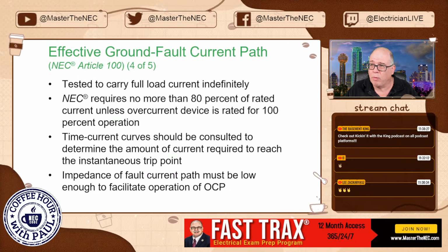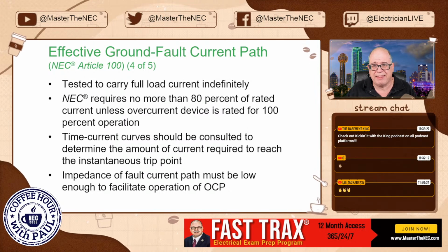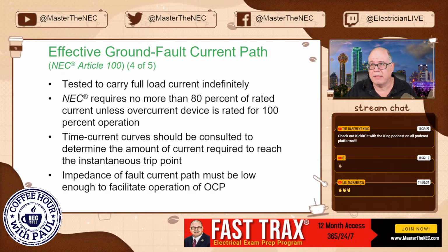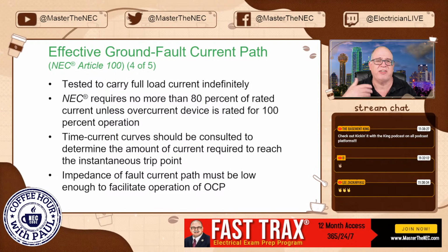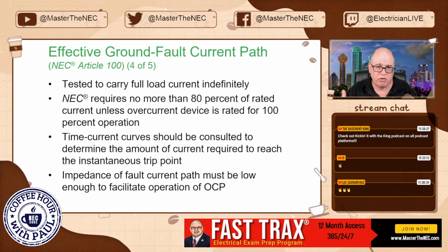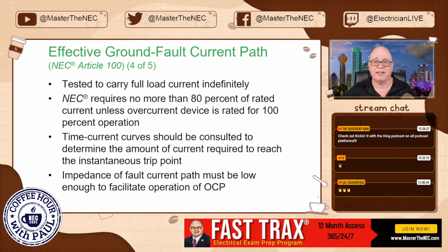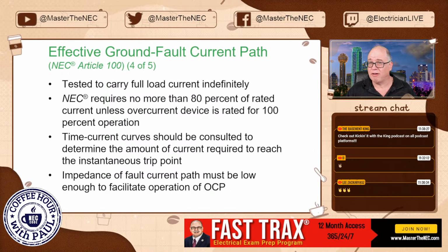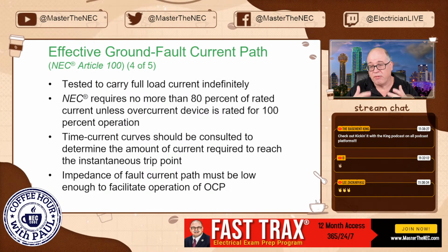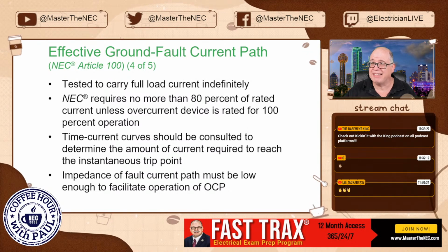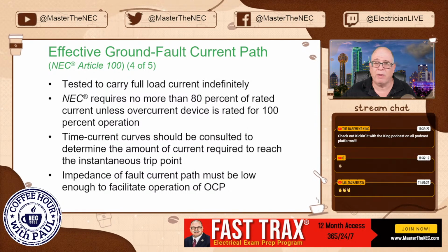EMT. So when people say, can I use EMT as an effective ground fault current path? The answer is absolutely. The Steel Tube Institute made sure that all those manufacturers were tested, and testing under the Gemini project at Georgia Tech was done years ago. It provides a very good effective ground fault current path as long as your connections are done right. If you have a conductor run and you size it right, you still have to make good connections, but you have many ways to do that.